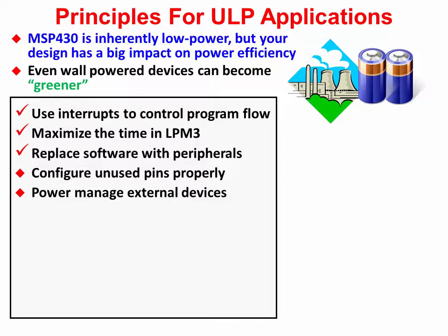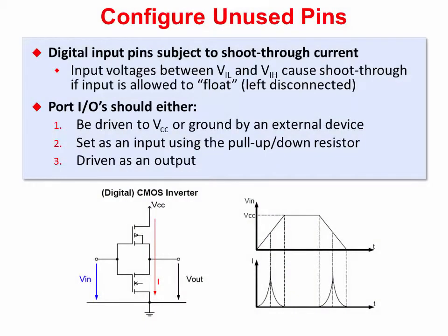It just depends on how your system is configured. But we can take a look at what to do with unused pins. If pins are configured as inputs, which is generally the default state for most processors, their state can end up floating up or down if left unused or disconnected. This floating state will consume power. In fact, we'll see this in the upcoming lab exercise.